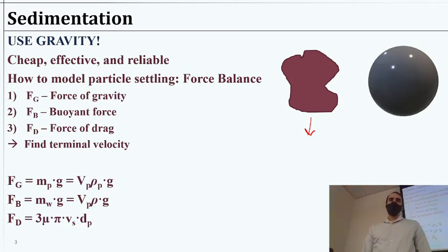In terms of the math, we can do math for type 1 sedimentation because we can simplify it with certain assumptions. The other types, we can't do math from first principles. We have to do observational, empirical work. Like I tested it this one day and it settled at this speed for a little while and then it slowed down.